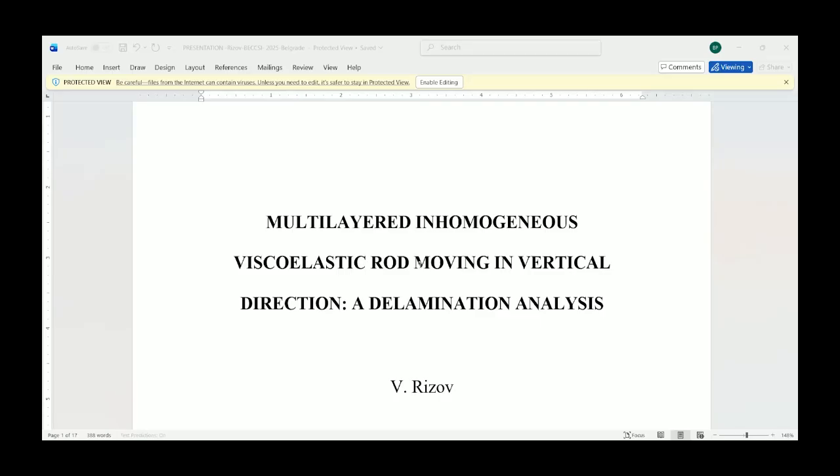The rod under the inertial loading has nonlinear viscoelastic behavior that is treated by a model structured by nonlinear and also linear springs and dashpots. The rod is made by concentric layers having different material properties and thickness. There is a delamination crack between layers. The crack represents a circular cylindrical surface. The complementary strain energy in the rod is determined and used to obtain the strain energy release rate.